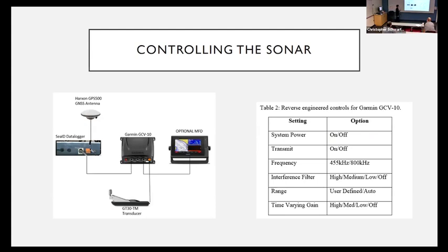To control the sonar is fairly trivial. Like I mentioned before, I was able to install Python on that little Odroid computer inside the data logger. And then I could build a library of Python scripts that allowed me to send datagrams with the command strings for the sonar controls.